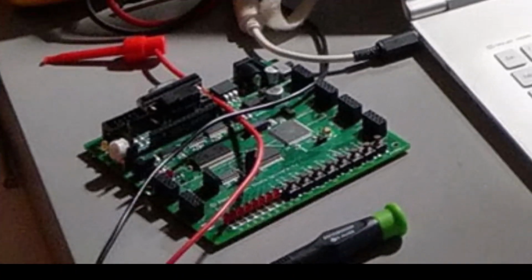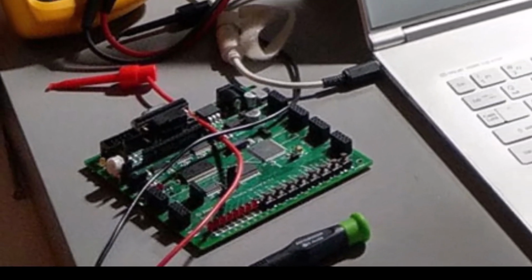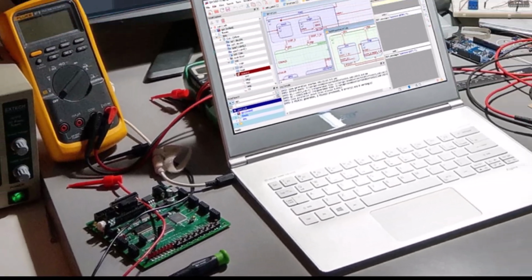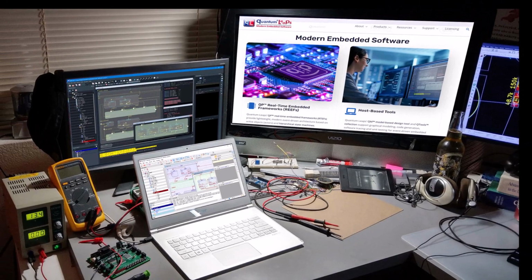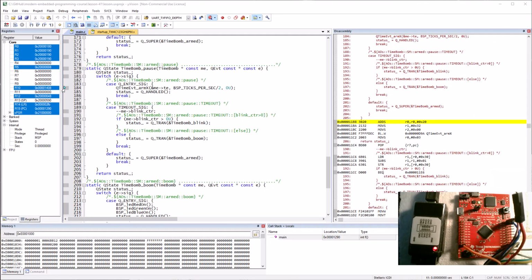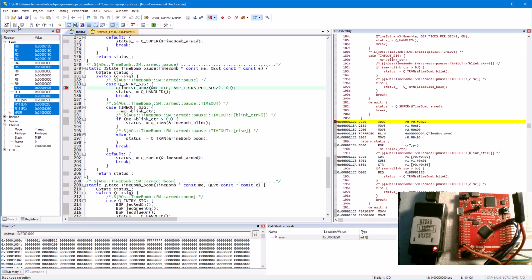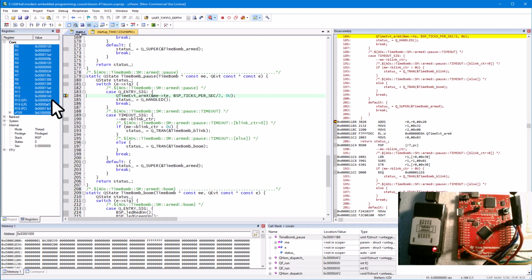In any real-life project, getting the code written, compiled, and successfully linked is only the first step. The system still needs to be debugged, tested, and optimized. So far in this course, the primary tool for this was the single-step debugger, where you set breakpoints and, after a breakpoint is hit, you inspect registers, variables, and memory. In case of any problem, the biggest question is always, how did I get there?